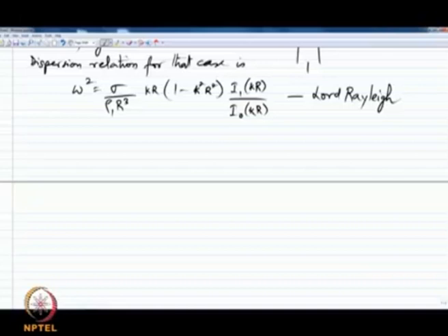But if perturbed by an arbitrary wave number, or let us say by a whole set of wave numbers between 0 and 1, then the wave associated with a wave number 0.693 is likely to grow the fastest. And the source of this growth essentially is surface tension energy.